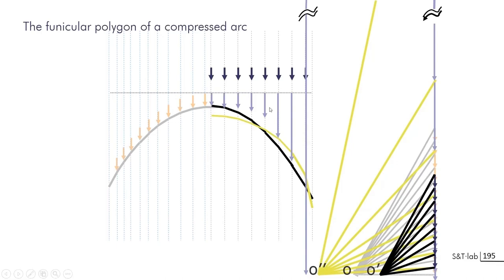A parabola is one in which we have just distributed loads on the horizontal. You could have here on the left the forces that have to be applied to equate this geometry, but for an arc of a circle, you see that it's quite complicated. So you know the orientation of each of these vectors by drawing parallels to each of the line segments of this line.